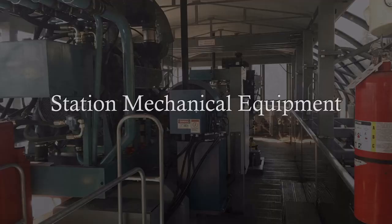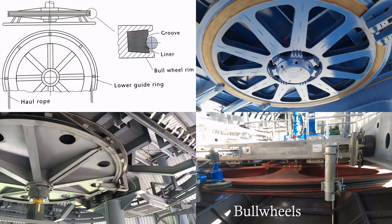The next component group is station mechanical equipment. This includes all of the mechanisms that power a ropeway, keep the haul rope under tension, and detach the grip for detachable ropeways. We'll start with bull wheels. Bull wheels are large metal wheels at the terminals of ropeway systems that are used to redirect the haul rope. They can either be drive bull wheels, which are powered, or return bull wheels, which simply spin to redirect the haul rope. On many fixed grip lifts, the bull wheel will be exposed. However, on detachable lifts, the bull wheel may be obscured by detachable terminal cladding.